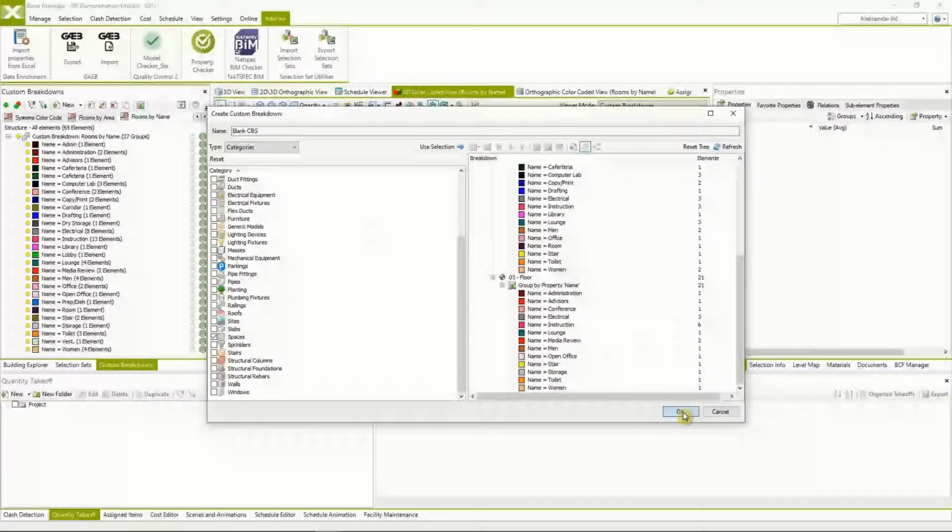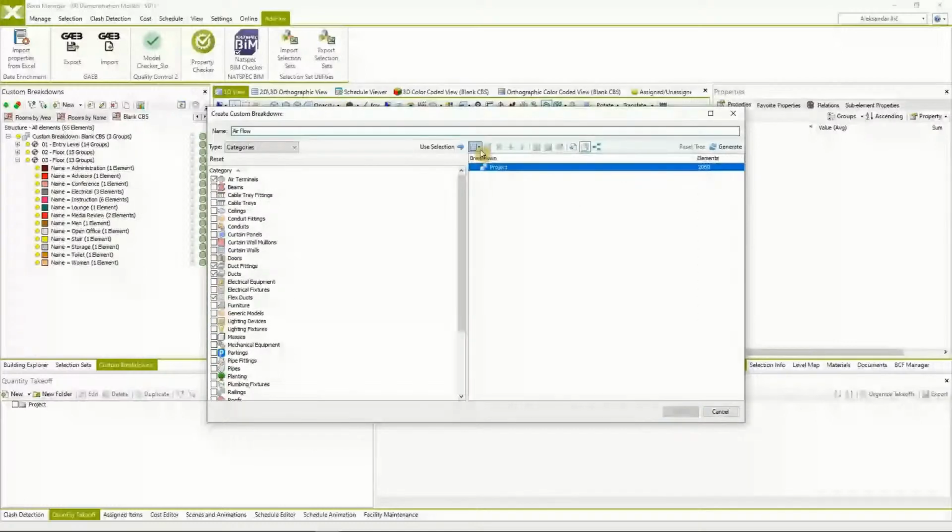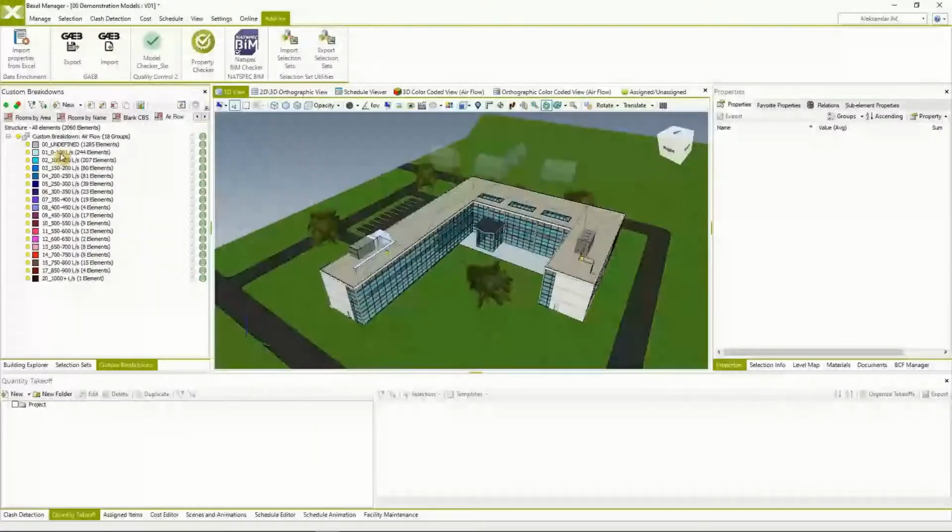So you can actually make a lot of different analysis based on this knowledge base. After we import the template, we can see that we again have certain elements that don't have identified value. You can right away see how this CBS template can help users start the quality control process of the model, to easily identify and visualize elements that don't comply with certain rules defined within your knowledge base. And you can easily visualize the data layer of the model through the 3D representation of the model.